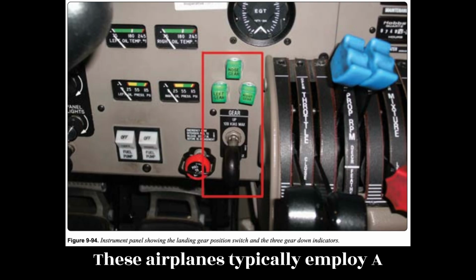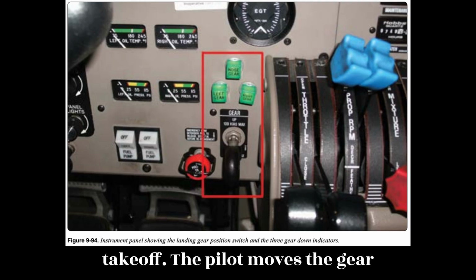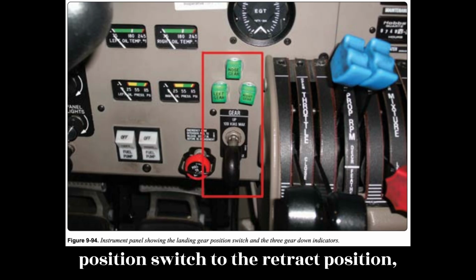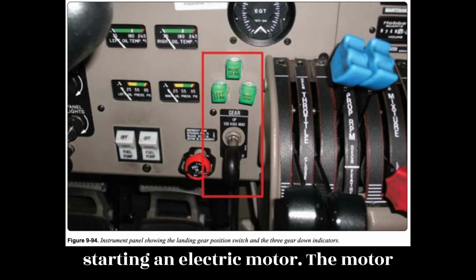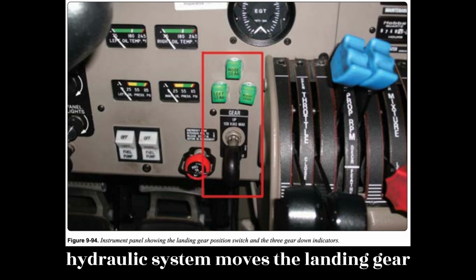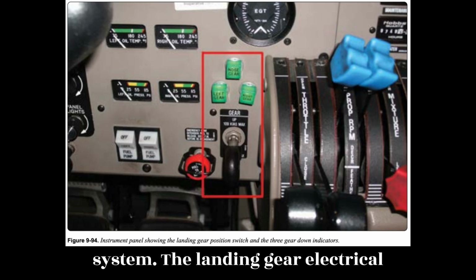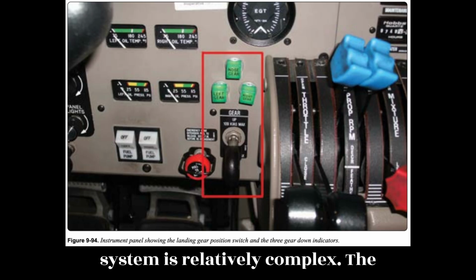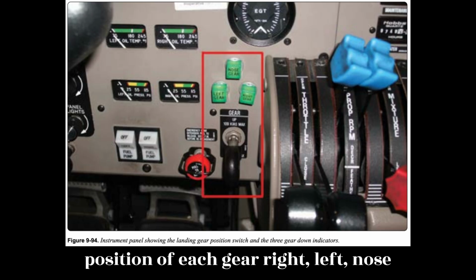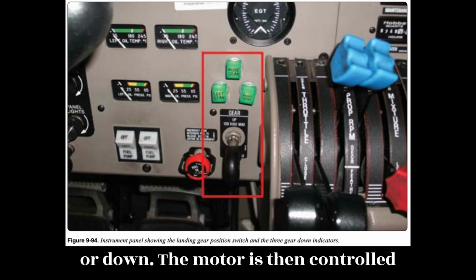These airplanes typically employ a hydraulic system to move the gear. After takeoff, the pilot moves the gear position switch to the retract position, starting an electric motor. The motor operates a hydraulic pump, and the hydraulic system moves the landing gear. To ensure correct operation of the system, the landing gear electrical system is relatively complex. The electrical system must detect the position of each gear, right, left, nose, and determine when each reaches full up or down. The motor is then controlled accordingly.